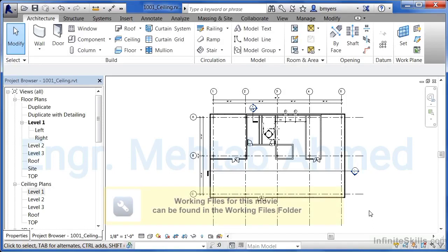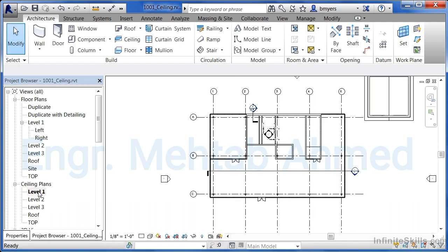Ceiling plans are used to document the way that a ceiling or the light fixtures up above a certain height are represented. Inside of Revit, it's not underneath floor plans that we need to be looking, but underneath ceiling plans. In this case, double-click on Level 1 to bring up what's technically called the reflected ceiling plan, looking straight up in Level 1.